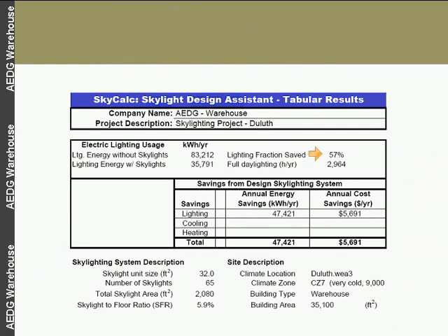We did model, again, every climate zone ultimately, and this is one area, if you were to look at the tables, you would see that in Fairbanks, we actually took the skylights out. It wasn't that we weren't getting energy savings. We were getting really good energy savings during the summer months. But the heating penalty, because we were trying to heat this building to maintain 50 degrees, if we had these large openings in the ceiling, in the winter months, it really was a heating penalty.